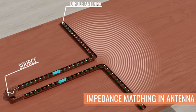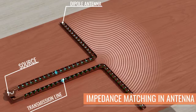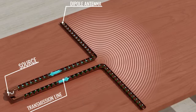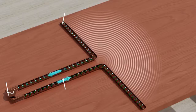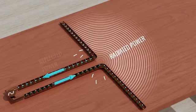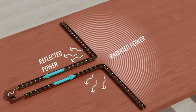Since an antenna works on high-frequency signals, the impedance of the transmission lines also becomes important. Hence, to achieve maximum power, the impedance of an antenna should match to the impedance of the source and transmission line as well. If the impedances do not match, some portion of the power would be reflected back to the source instead of radiating outwards from the antenna.